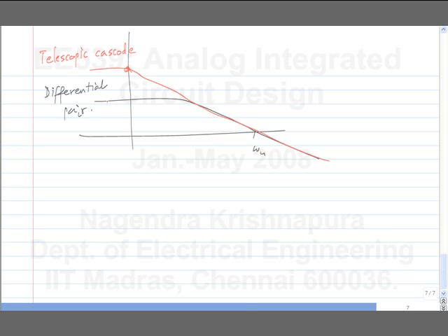Okay. The question is, why will the unity gain frequency remain the same when we have added so many transistors and their parasitics? I am now assuming sort of zeroth order analysis where the capacitance is dominated by whatever load we have. Okay. In that case, it will not change. That's true. The transistor size in a cascode amplifier and in a regular amplifier may be different. So, internal frequency response will be different, and this has so many other nodes. Okay, at each node you expect a parasitic capacitance. So, you expect a lot more poles and zeros in this case than in the differential pair. But ignoring all of that, you do get to a first order the same unity gain frequency.